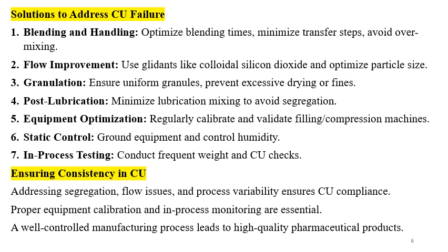Equipment optimization: regularly calibrate and validate the blenders, and validate the filling and compression machines. Static control: ground the equipment and control the humidity. In-process testing: conduct frequent weight and CU checks. Stratified sampling is required, to be done for capsule filling and for compression of the tablets.